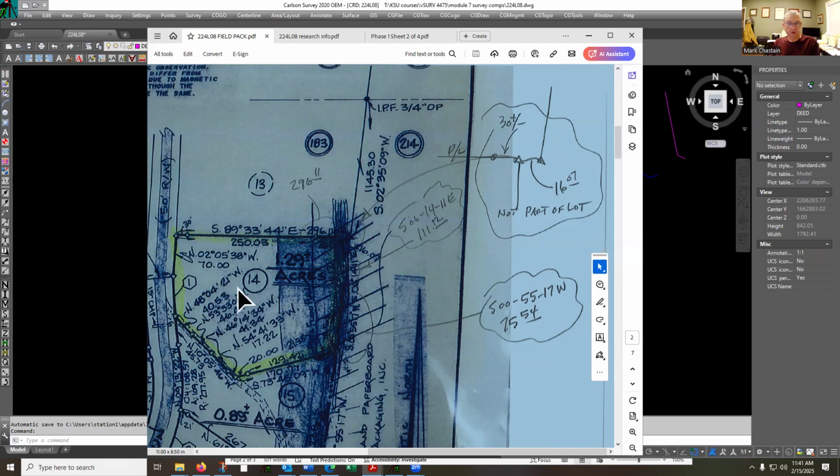A lot corner in a platted subdivision meets the requirements of a point of reference, if you want to look back at the technical standards for maps and plats. Sometimes running off 1145 feet behind an old toll station survey may just create more problems than it solves.